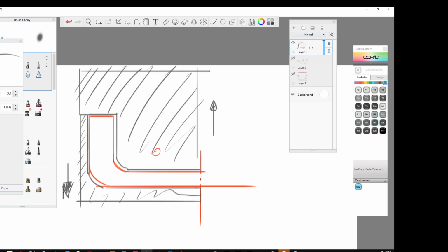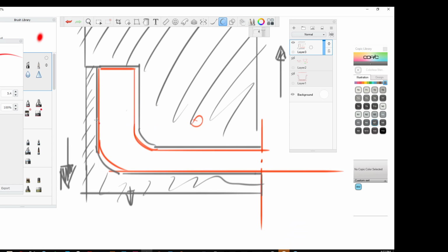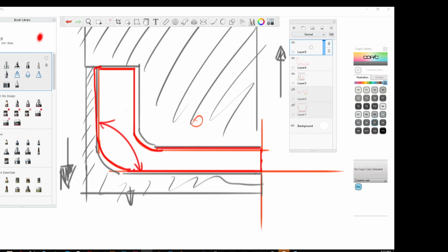Okay. So, with that said, if this tool is going down this way, we need to have draft on this wall in relationship to here. Let's do this. So what that means is we have this part here, and we're going to want to have some draft on there to make this easier to come off. So what that means then is that our tooling part is going to have that draft. That's what creates the draft.